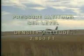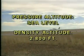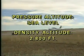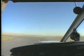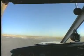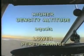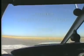This computed density altitude value means your airplane will perform as if it were departing an airport nearly 3,000 feet higher than the one where it's actually located. Because the density of the air is so much less with this above standard temperature, your airplane's performance will diminish. It's important to remember that the higher the density altitude, the lower the airplane performance.